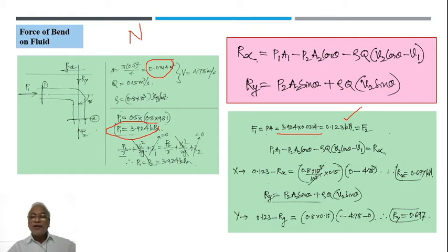Now if you look at this rho, which is in kg per meter cube, you have to understand in the beginning only these things. That's why this is kg per meter cube multiplied by Q in meter cube per second. So it becomes kg per second.